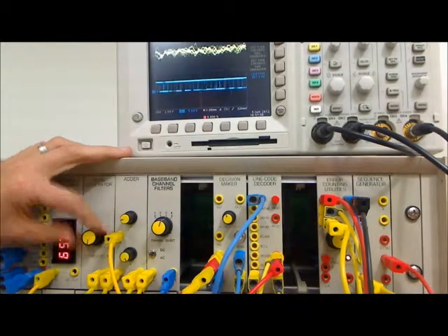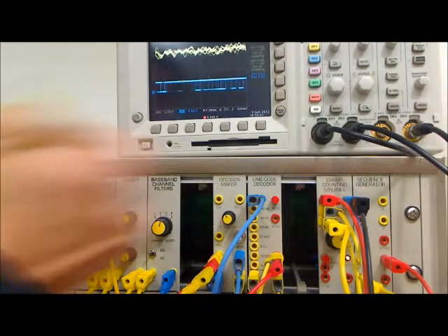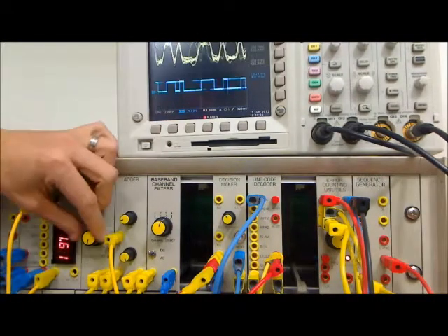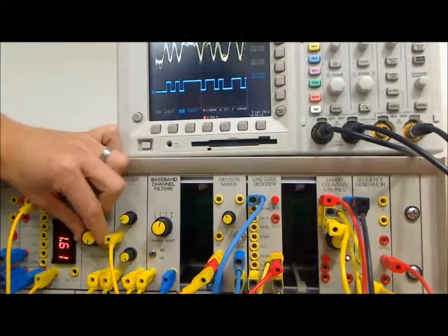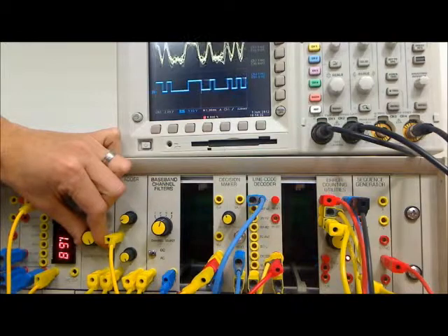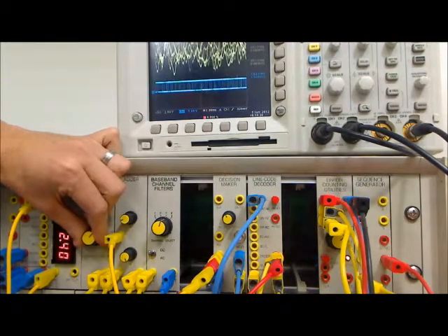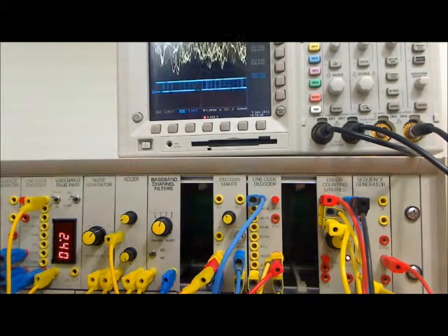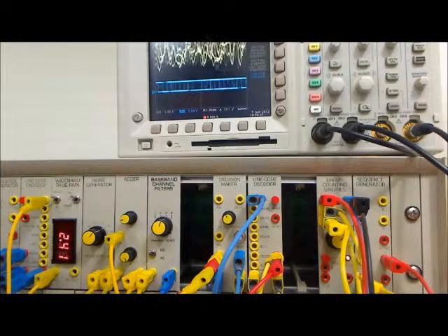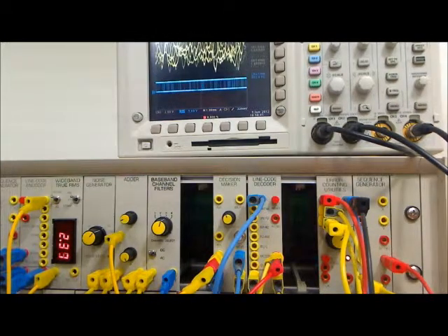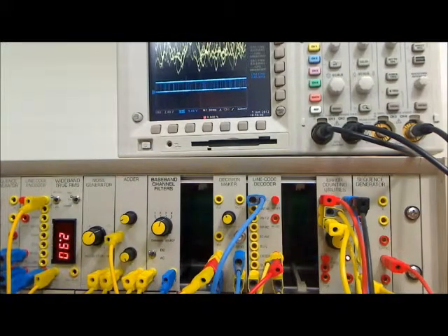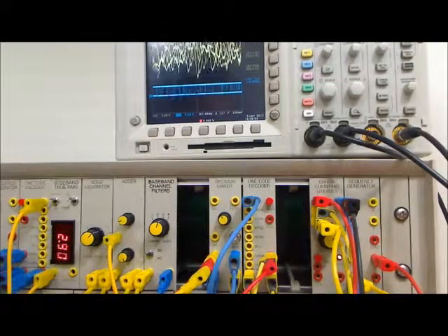So now, using the calibrated knob on the noise generator, we can easily move in calibrated 2 dB steps. We have a reference measurement of 6 dB. We can simply take the rest of the measurements off the true RMS meter step by step with the noise generator. It makes it very easy for students to take multiple measurements to define the bit error rate performance curve. So what we have, briefly, is a procedure for taking bit error rate measurements in a noisy channel at baseband, and if you want to work at bandpass, you can add modulation and demodulation for viewing other passband schemes and quadrature schemes.